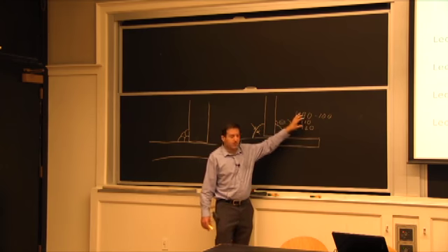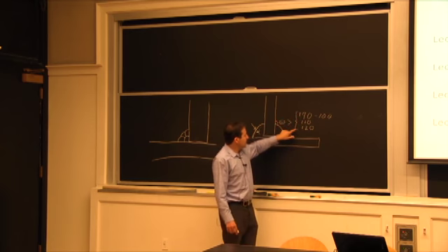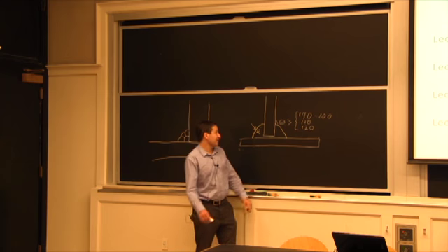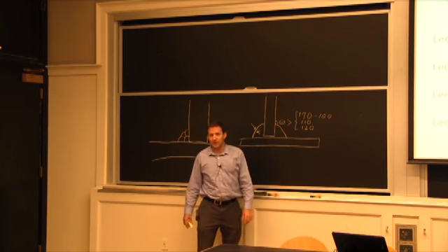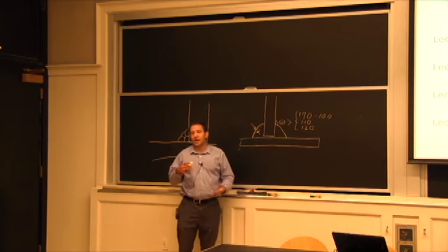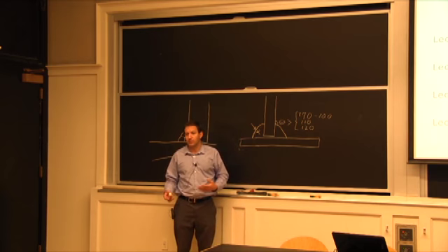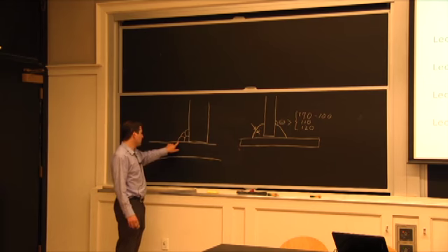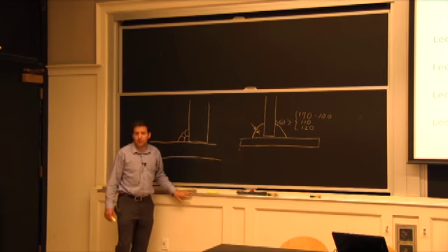If you came out and say 90% of the time they're 120 degrees, but 10% of the time they are 90 degrees, well, that tells you you can't rely on a single connection to be fully reliable, because when you go to 90 degrees, this type of situation, you don't have ductility typically.